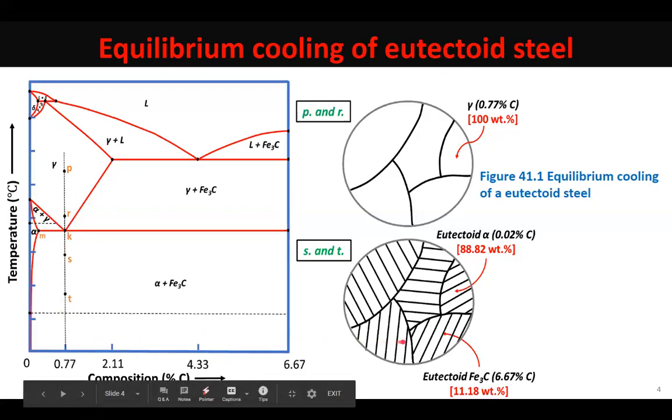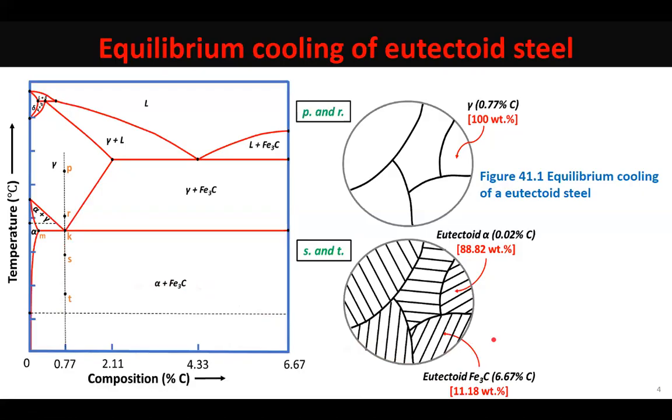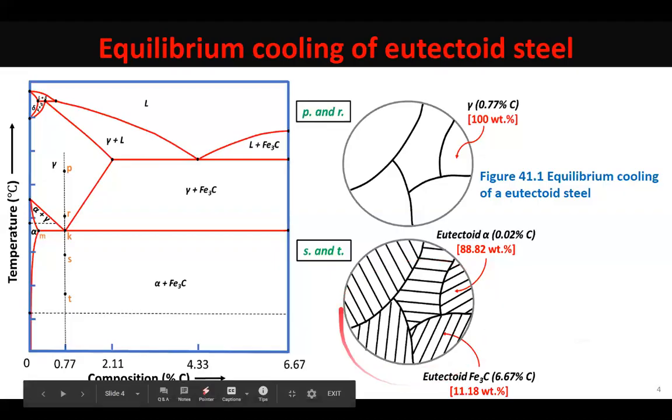So what you see is that some more amount of cementite gets formed, but students, the amount of this additional cementite that gets formed because of precipitation of carbon out of ferrite is so small that it is insignificant in amount, and we do not show any changes happening to the microstructure practically.